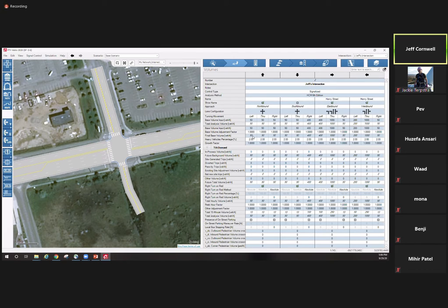adjustments to vehicle volume. One thing that's important that I might show on future assignments when we get into more complicated things is you'd add the heavy vehicle percentages. So these would be a percent. If I give you a number, you'd have to convert it to a percent, or if I give you a percent, you just add it. 2% seems to be standard. If you thought you maybe had higher volumes for some, you could raise them up if needed. So there's an example, I could put 4%. So you put this in per movement.